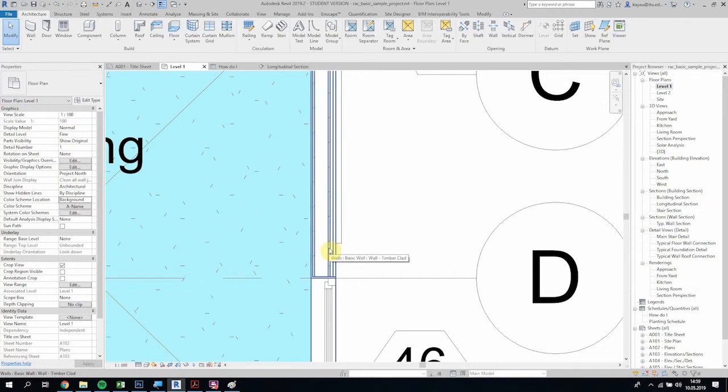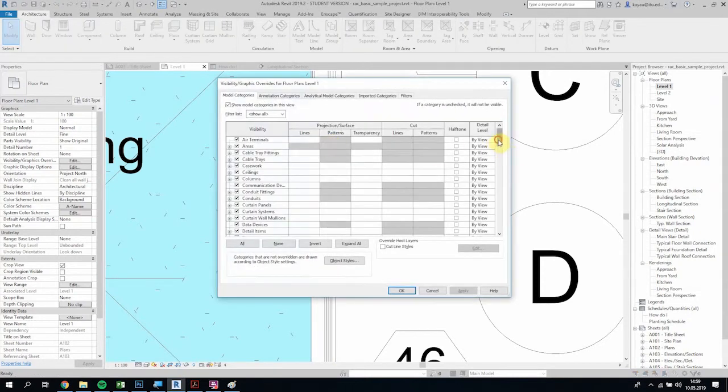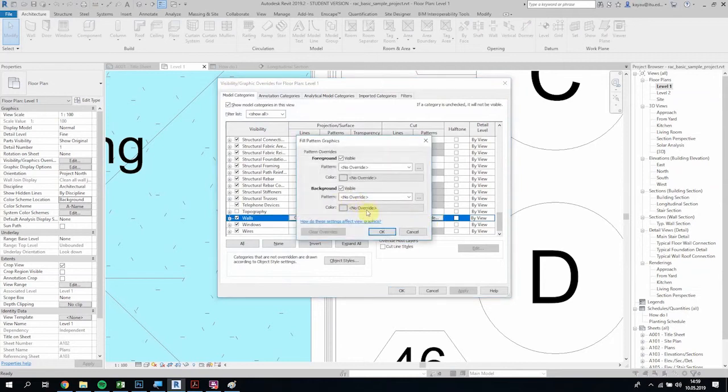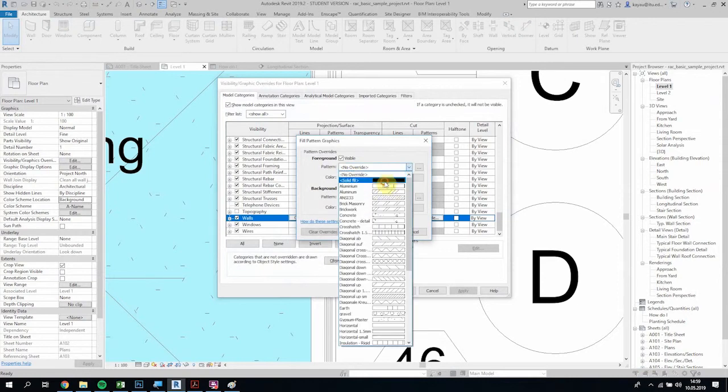And if you still want to see the assembly lines, the separations, but at the same time you want to color the wall, for example yellow, you will use background. That means it will not affect the lines at the top. If you want to see everything in yellow, come to foreground. Let's make foreground in this example.